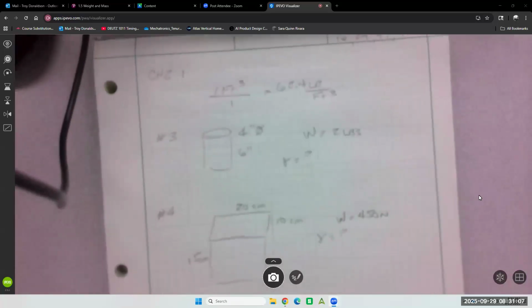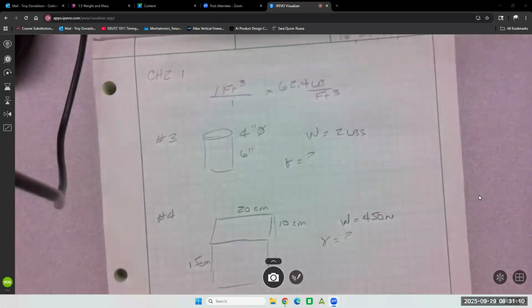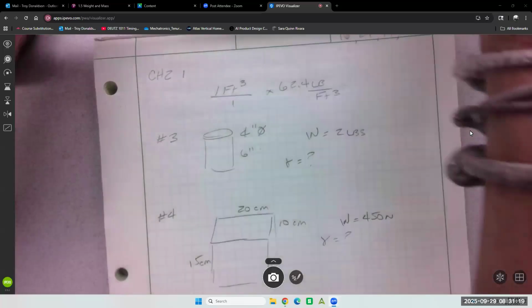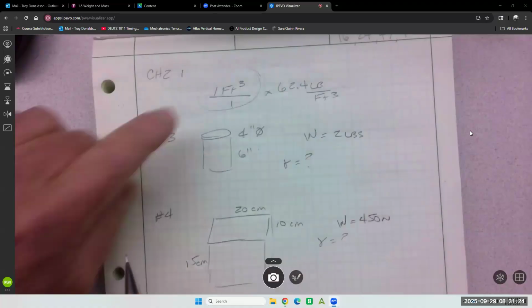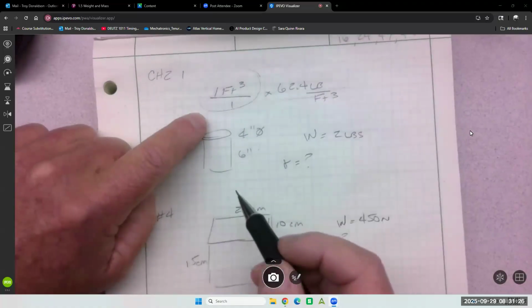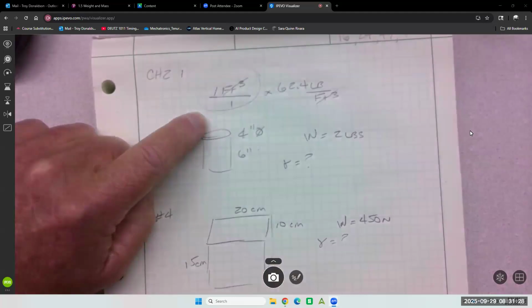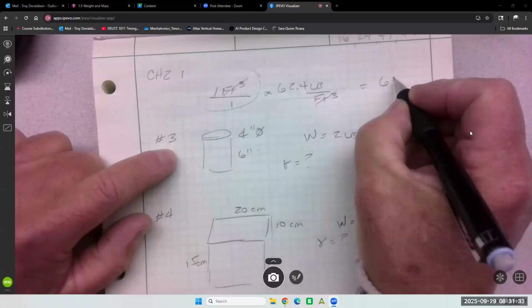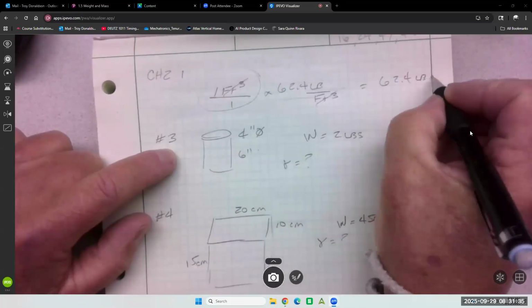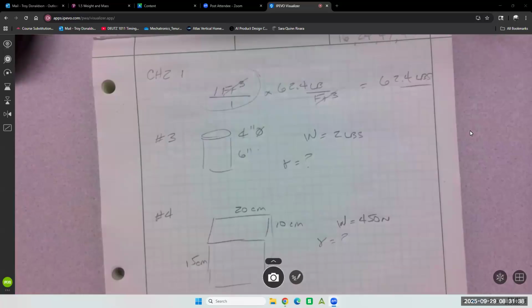First question was kind of silly. 1 cubic foot of water. All you need to know is the specific weight of water, 62.4. And then it's good to show the unit analysis. We want to get in that habit. So the unit analysis would be, okay, this is what I have, this is what I'm using, water, and I want these to cross the volumes, right? 62.4 pounds. So that was pretty straightforward.